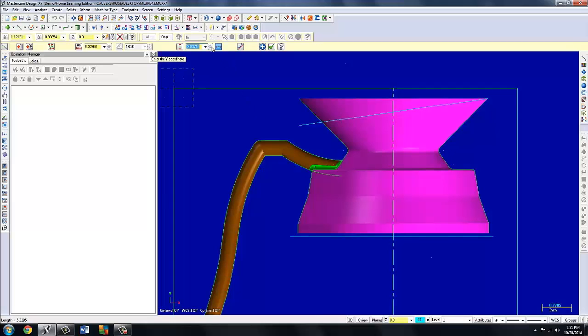I look at my drawing and I see that my distance from the actual origin here is 6.5 minus 2.75, so my distance is negative 3.75. We need the negative in here because we're not doing a parallel distance, we're doing an actual coordinate number. So put that in, enter, and there it goes. I'm going to check out of that, and I'm going to extend this one past a little bit too, just like we did on tutorial 4. Get out my scissors. Let's do a 0.2 and pick the line up at this area, and there we have that. Now we can create our draft surfaces from there.